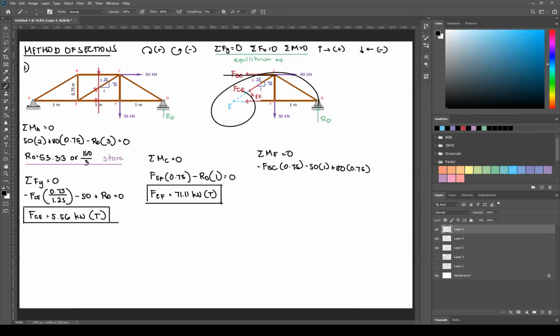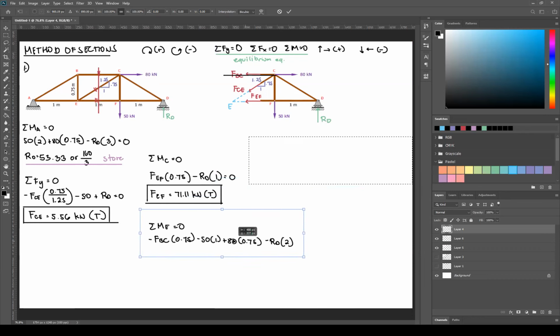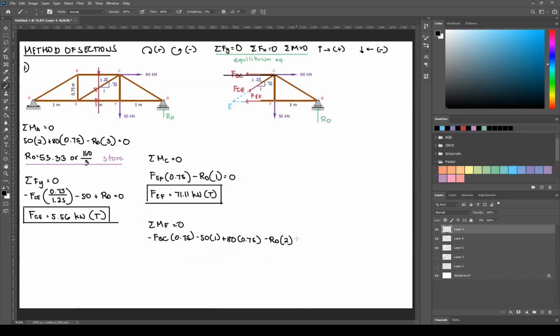And finally, we have RD, rotate about E, that's counterclockwise. So negative RD. Perpendicular distance, again, you can refer to the original drawing. This is RD. Perpendicular distance is 2. So times 2. There's no other force. So we can already equate this to 0. Okay, and then from this, you can solve what's FBC. Oh, wait, sorry. 50 is actually clockwise, so this should be positive. Correction.